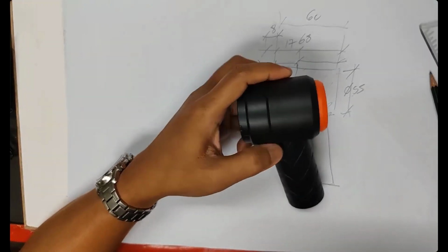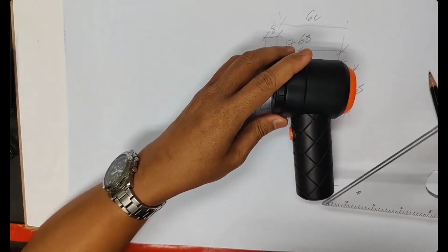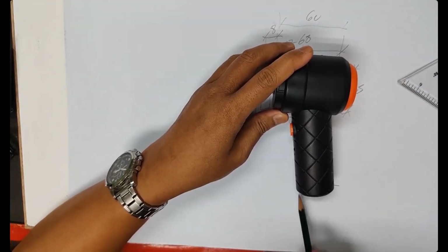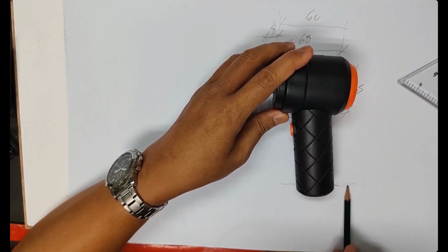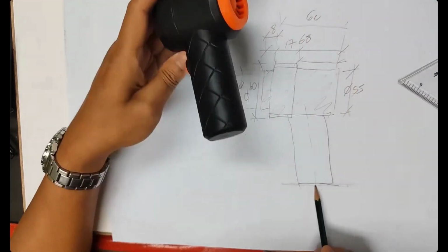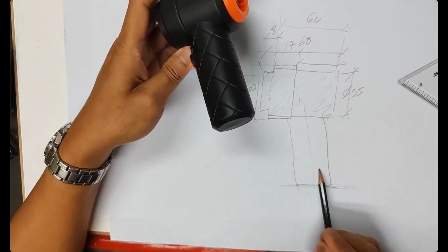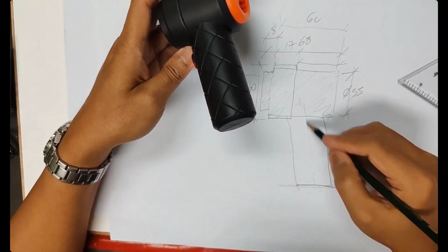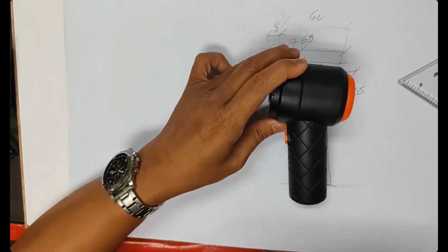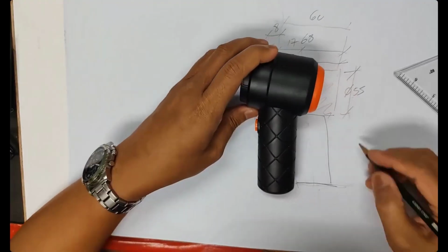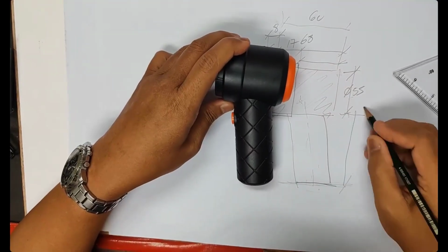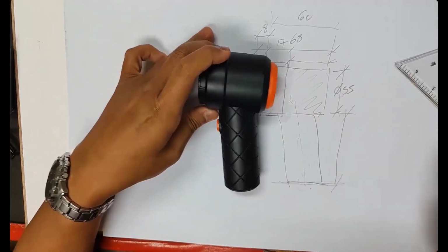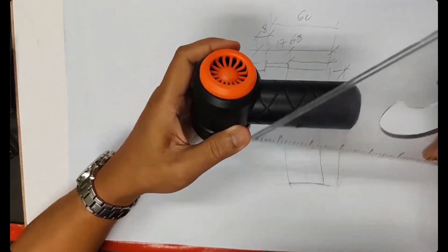Okay, look here. I have a cylindrical body and how do I do the handle? I will add this plane. This plane in Solidworks is located here. Make a circle, extrude to surface or extrude up to body. I will show you up to body, up to surface. But the direction is this. So what is the distance? Okay, I just want to know the vertical dimension, not the angle. You see my sketch, the vertical dimension.